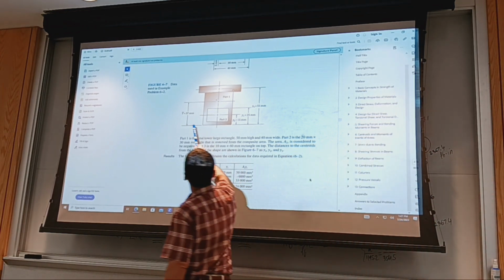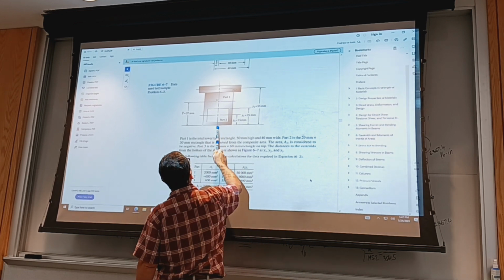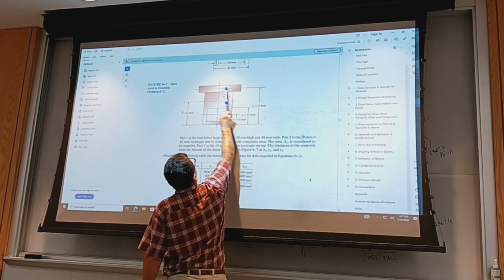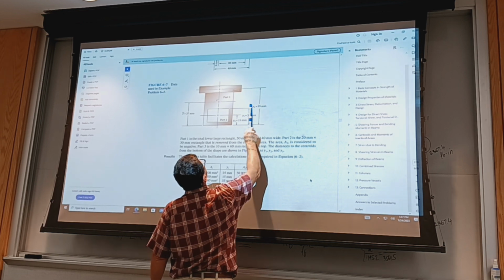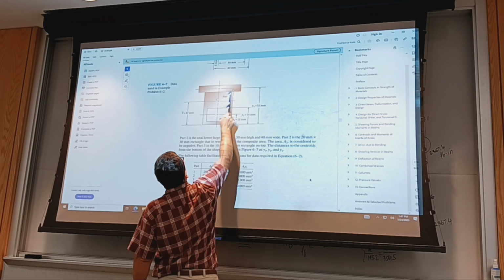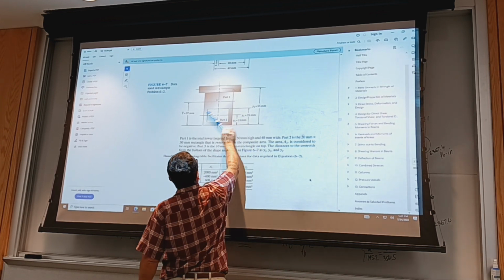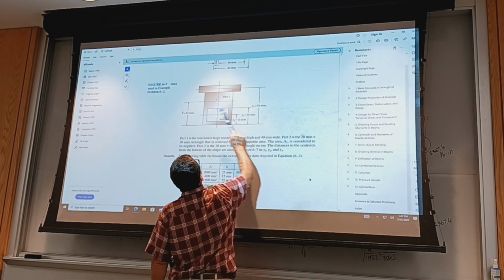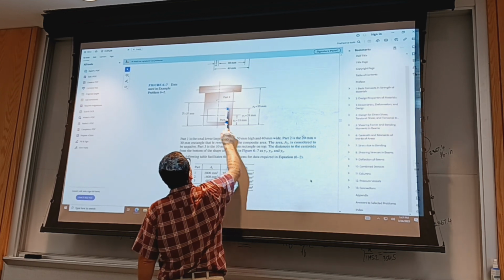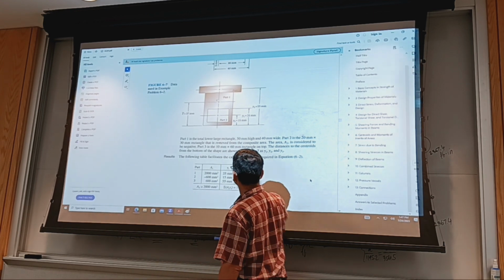Usually it's taken at the bottom to work with positive values. So what is the centroid of the top part? It will be 55, that is y3. Where is the centroid of part 1? Again, the rectangle without the missing part is 25, that is half of this. And where's the centroid of part 2? 15. You populate this table.